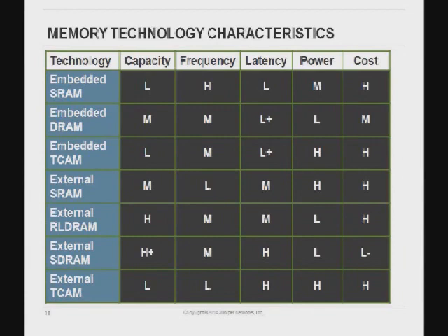The advantage of them is that they have exactly predictable latency. No matter how big the table is, you send them a content, they will return the address in the exact same time. But the disadvantage of them is that they are smaller, they have lower performance, and they have much, much higher power. And because there are not many vendors doing that, they are also very high cost.